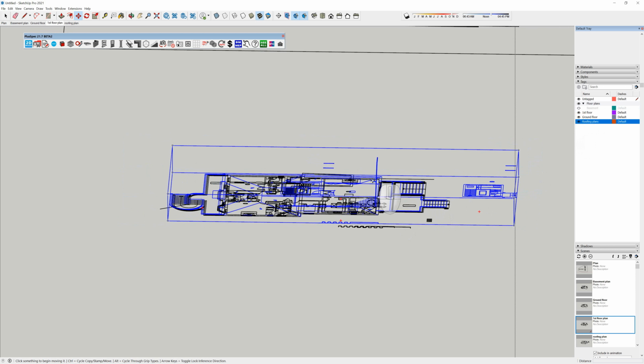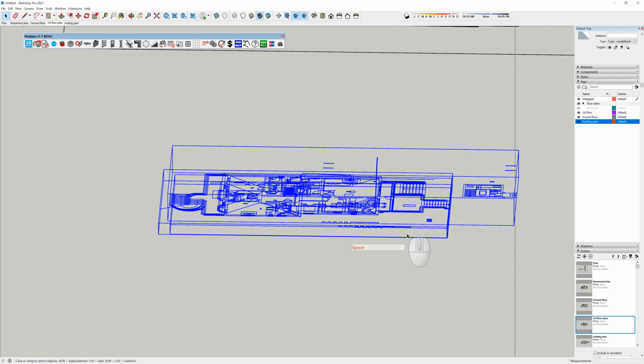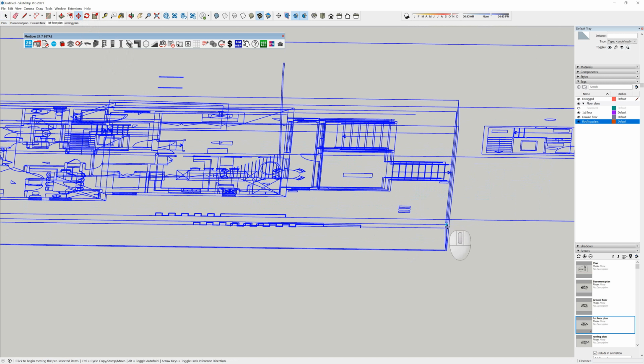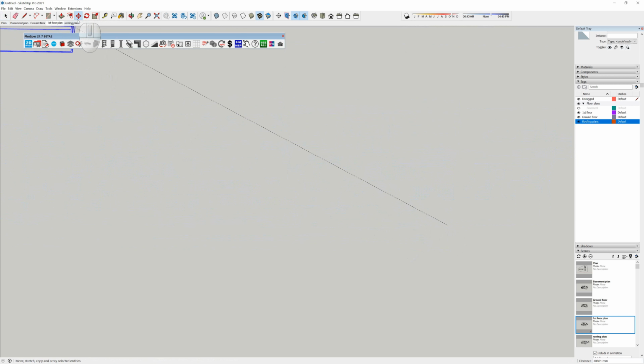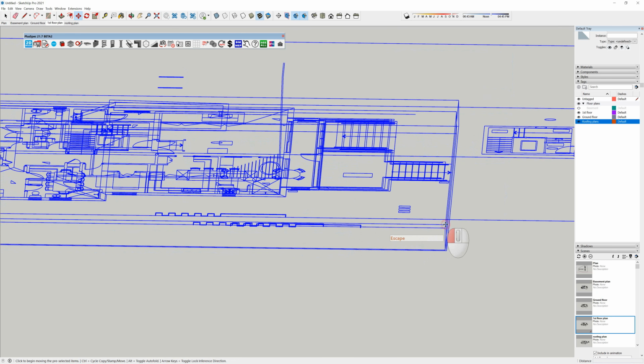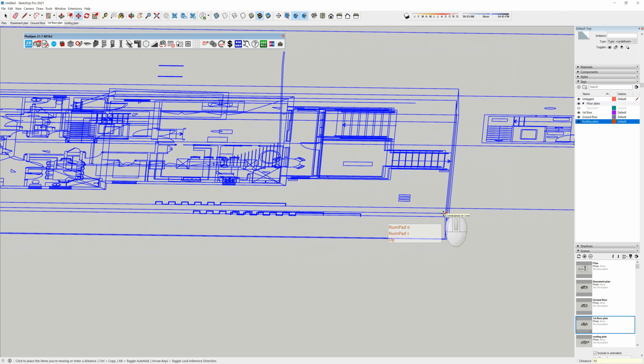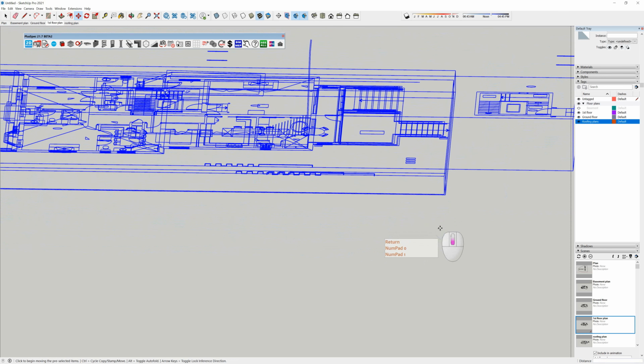Now that I have 3 sets of plans, and this set of plans is actually done in Imperial, I'm going to move all of these plans up the distance of the ground floor walls. I'm just going to assume at this time that it's 10 feet. You should be checking your elevation. So I'm clicking on the corner and I'm going to go move, which is here. I'm just going to escape because I don't want to move it that way. I'm going to move up. So I click my up arrow button and I type in 10 feet, or 3 meters or whatever it is.